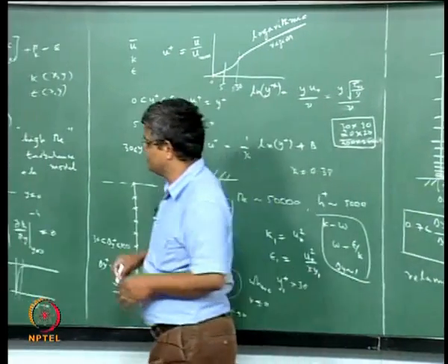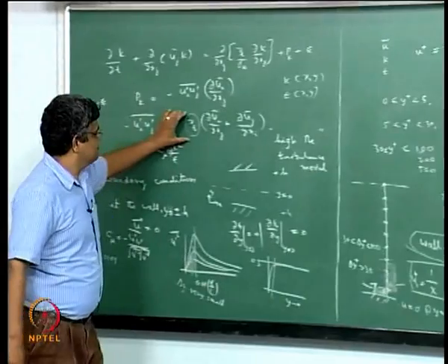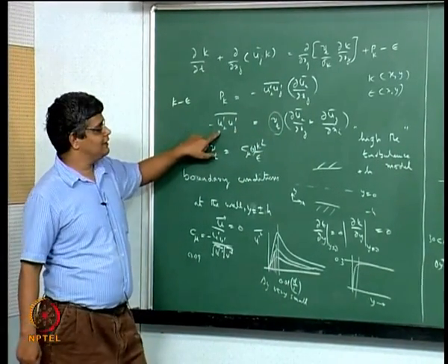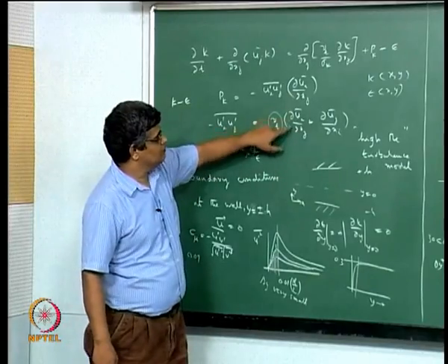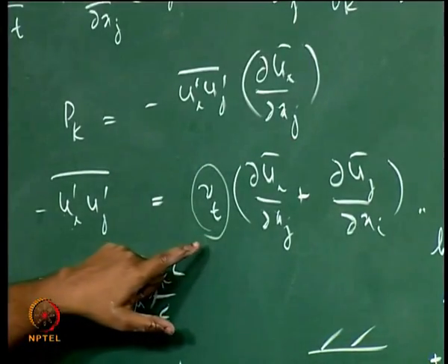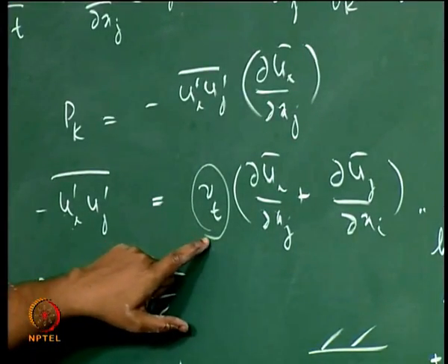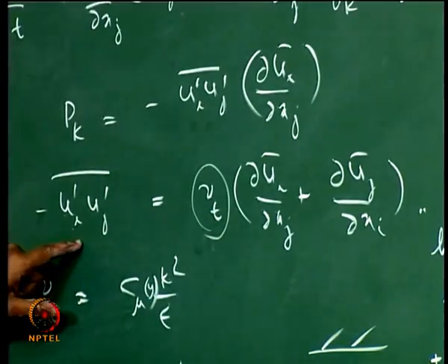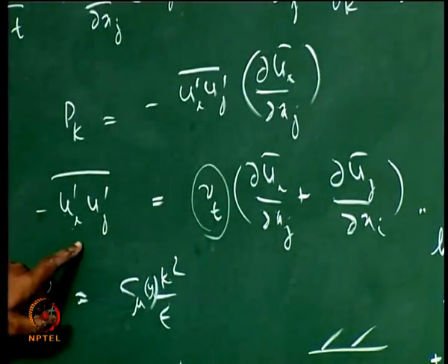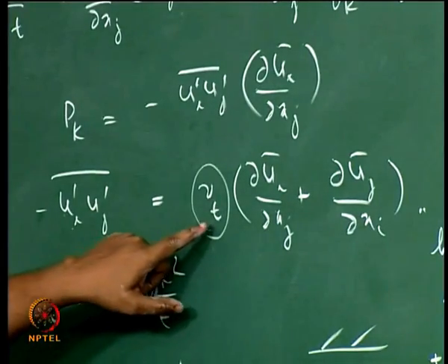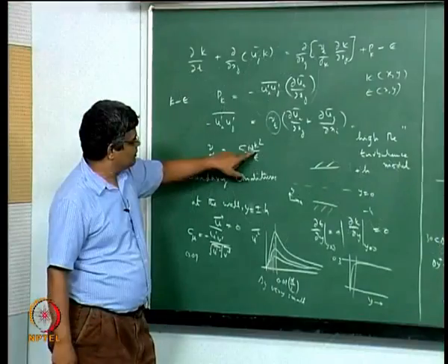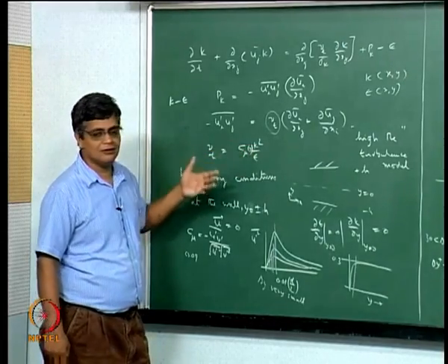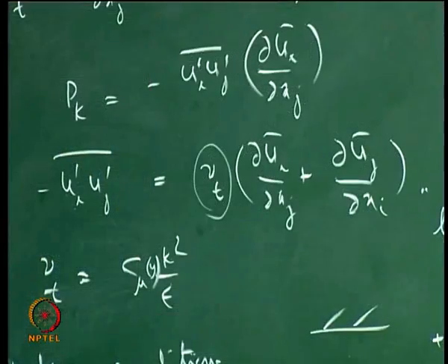Another problem with this is the assumption of isotropic viscosity. The turbulent stresses here are proportional to the mean velocity gradients through an isotropic viscosity. Isotropic viscosity because this viscosity is independent of which of the 6 stresses we are considering, and this is isotropic because this is determined only by k and epsilon, which are again scalar quantities, and therefore in that sense isotropic.